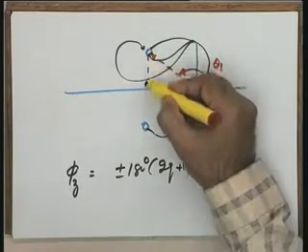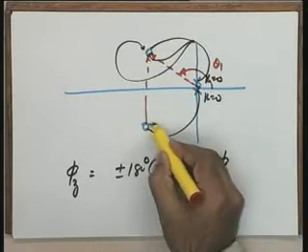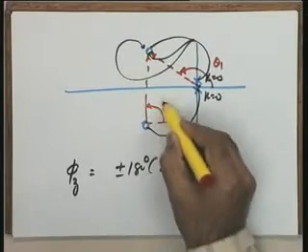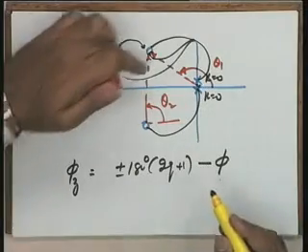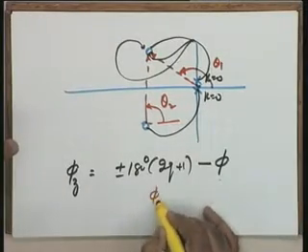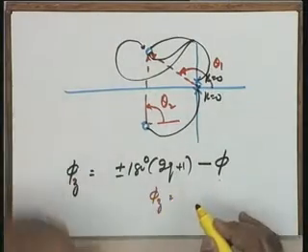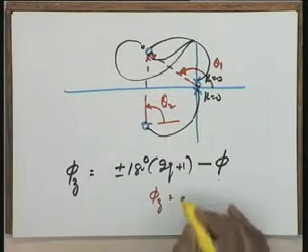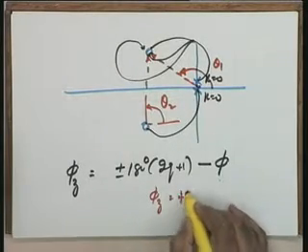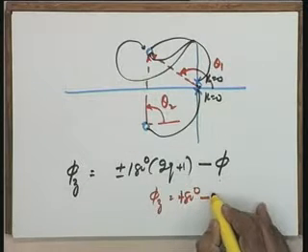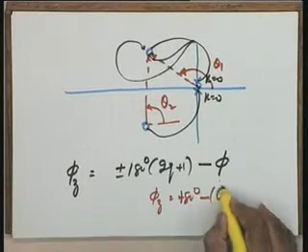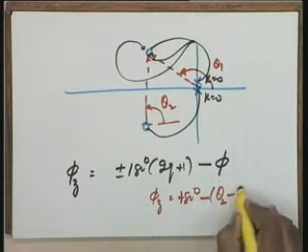You join this zero with this, make this vector, and the net angle contribution due to this zero is theta 2, which is equal to 90 degrees. And therefore, in this particular case, your phi z, the angle at which it will leave this complex zero, is equal to 180 degrees minus or plus sign you can take minus phi. Phi is theta 2 minus twice theta 1.